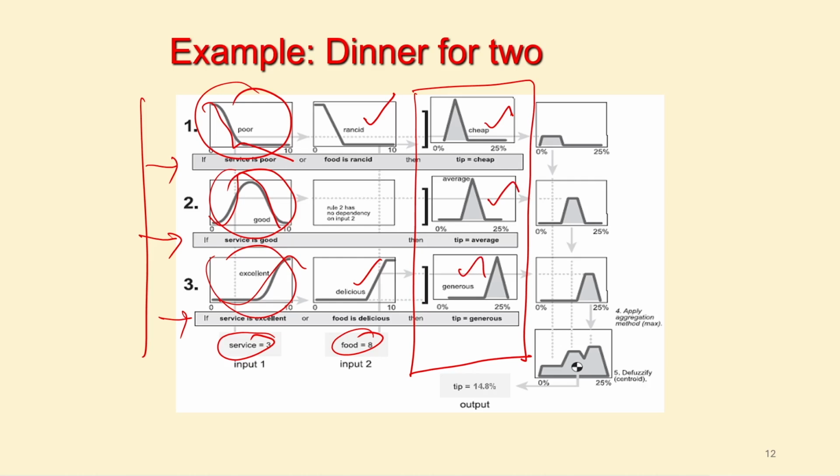After applying the cut point value, that is the min method, we have taken this one, and overall we have to apply the max operation, that is the aggregation operation. This has come down, and here we have to take the defuzzifying method, the centroid method, and this centroid method will give you the output. The output is 45. So this is what the rule viewer or the entire fuzzy logic toolbox supports, how the fuzzy concepts have been fired or explained for this idea.